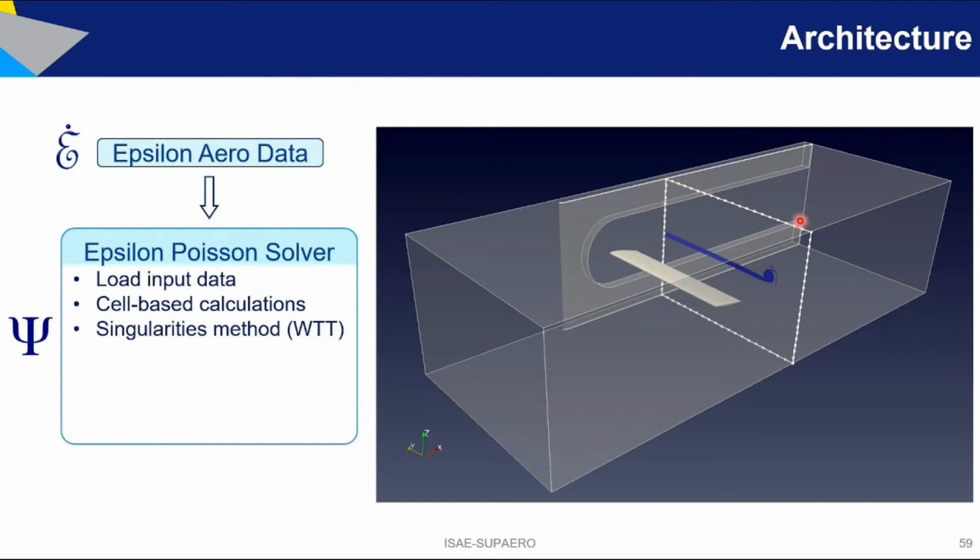And all along this line, you generate a sort of paneling, and at each one of these panels, you have to define circulation, and you check that at each control point, the normal velocity associated to the velocity induced by these singularities distributed on the entire surface, plus the velocity induced by the vorticity distributed wake, must give a normal velocity 0, which is the non-penetration condition.